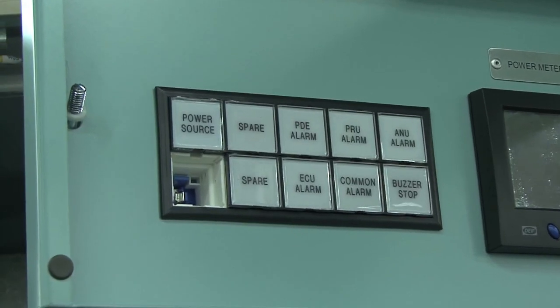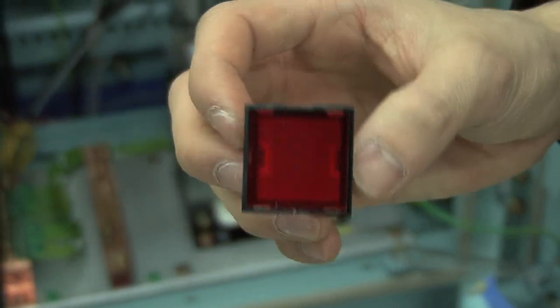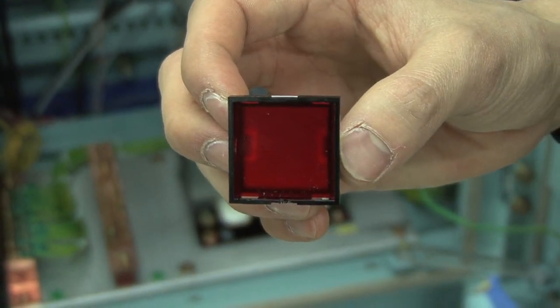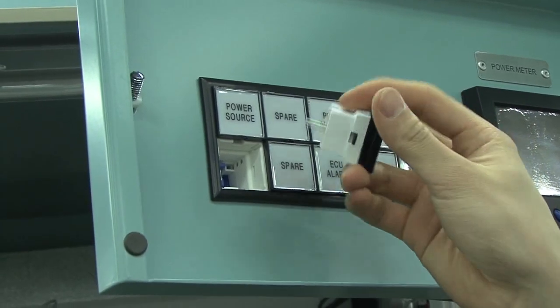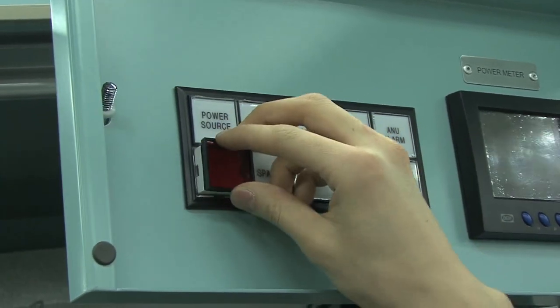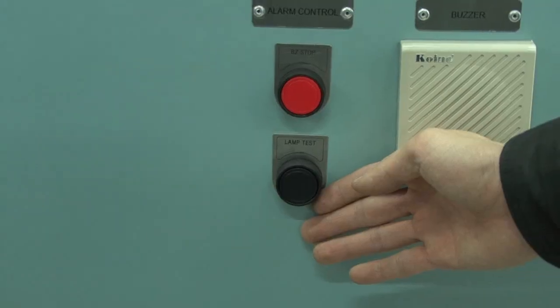Indication lamp. Applicable equipment and location: PDE. Step 1. Disassemble the lamp part and acrylic cover with a screwdriver. Step 2. Remove the lamp from the lamp part with a screwdriver. Step 3. Check the socket and voltages of a new lamp and reassemble the lamp, following instructions in reverse order from Step 2 to Step 1.